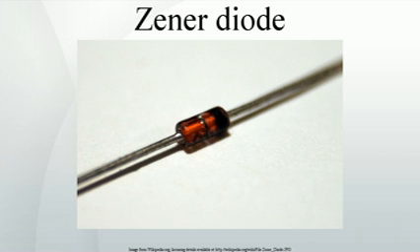If the current through D is ID, its breakdown voltage VB and its maximum power dissipation PMAX correlate as such. A load may be placed across the diode in this reference circuit, and as long as the Zener stays in reverse breakdown, the diode provides a stable voltage source to the load. Zener diodes in this configuration are often used as stable references for more advanced voltage regulator circuits.